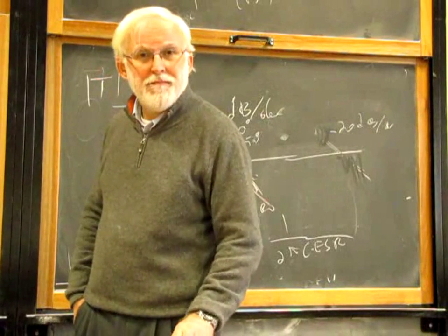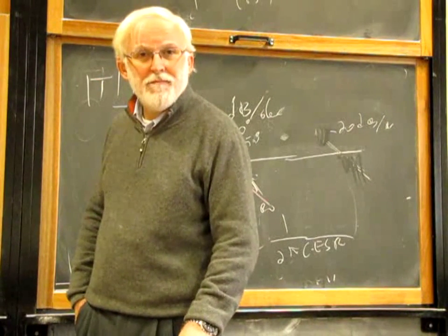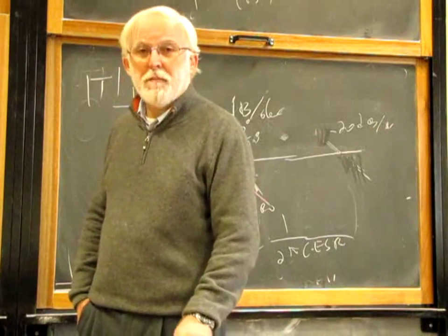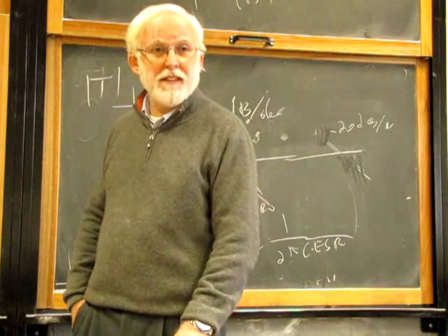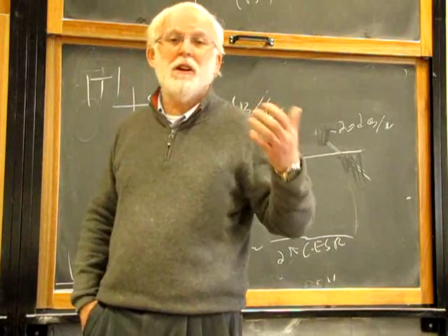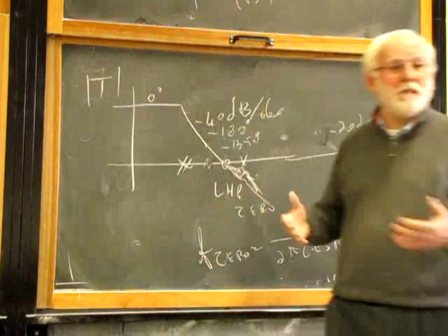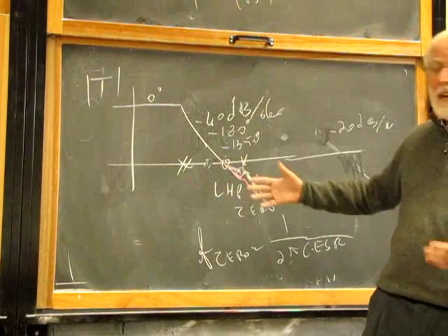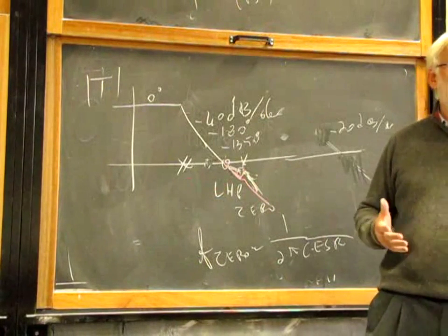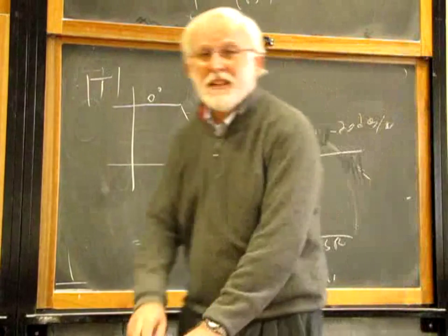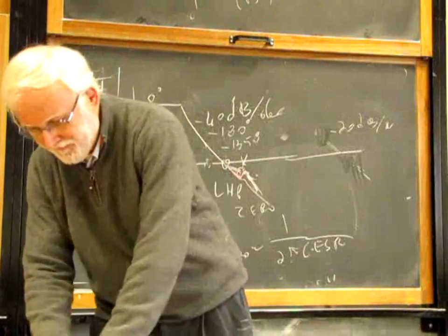So a better capacitor gives you better performance, less ripple and things like this, but you have to know where the 0 is. It's not the better capacitor that makes my system unstable. It makes your system unstable because you didn't design it to work with that capacitor. If you design it properly, this doesn't happen.